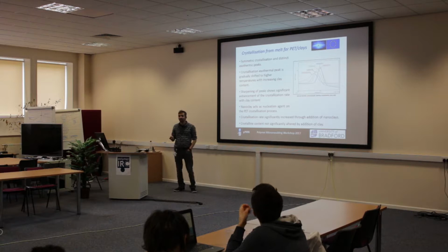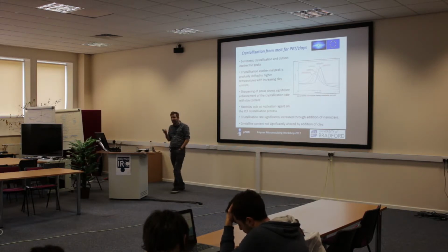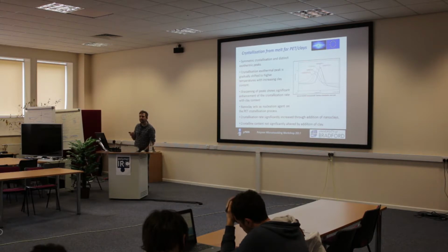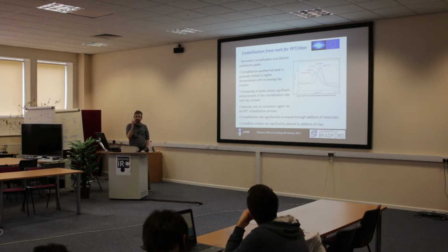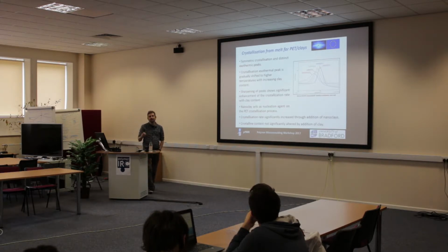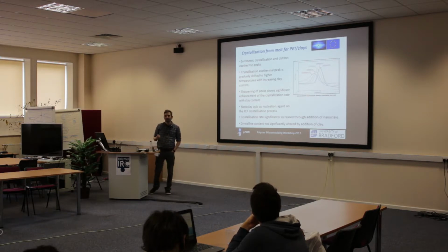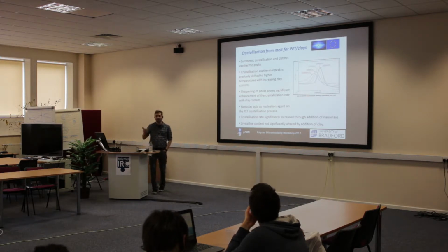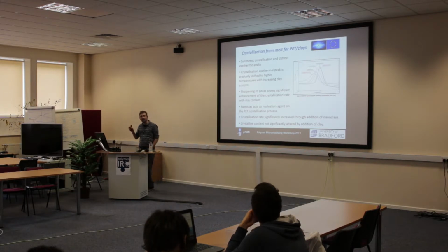how fast this material will crystallize. Now in micromoulding, you can pull out, I think it's 10 to the 6 Kelvin per second, because you're looking at a very, very small part. You've got Peltier cooling, so you can rip temperature out very quickly. But sometimes that's not always the best idea. Reduction of cycle time isn't necessarily the gold standard that we need to achieve.